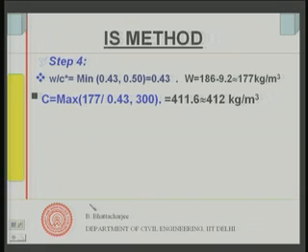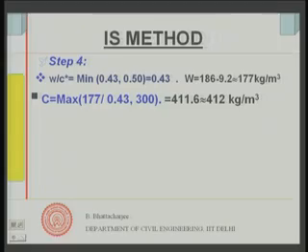That is the overall adjustment in water content, and the volumetric percentage of the fines in total aggregate, right. So, now with these corrections we can find out the change in the total water content and the total fines.